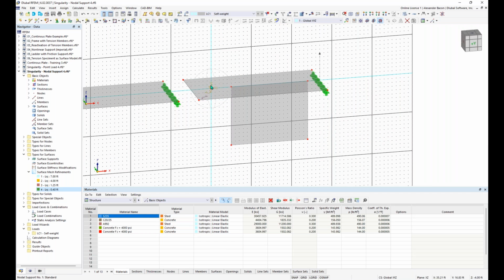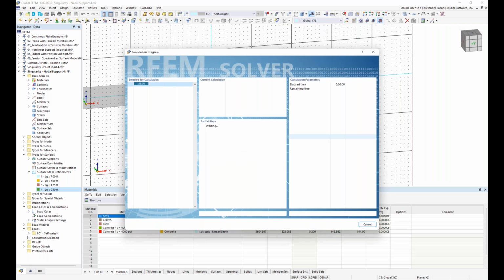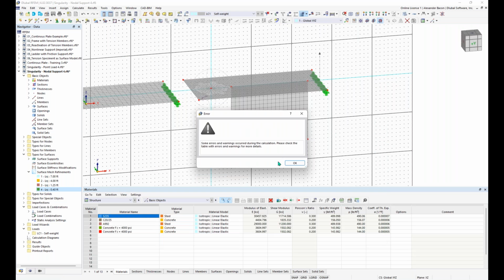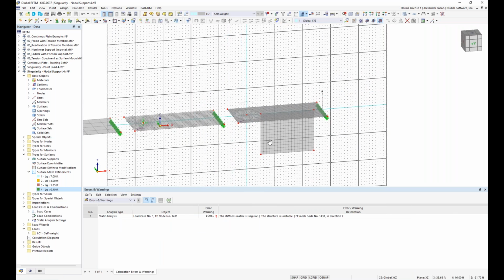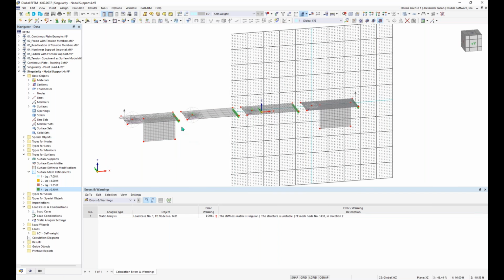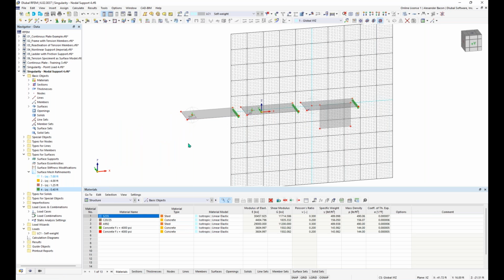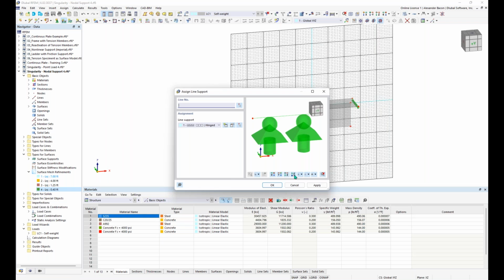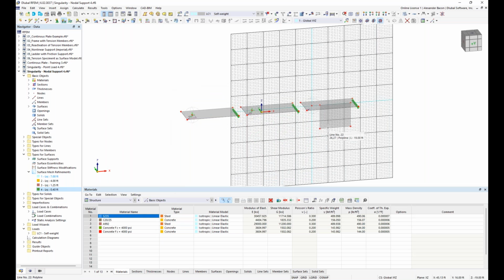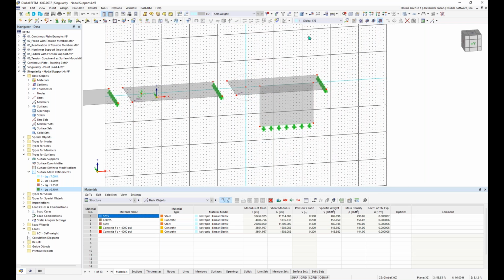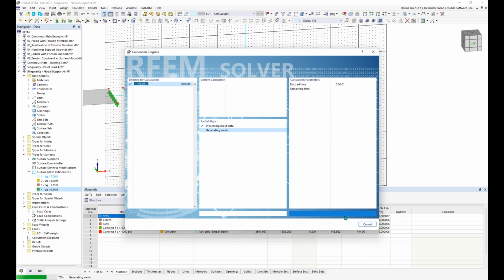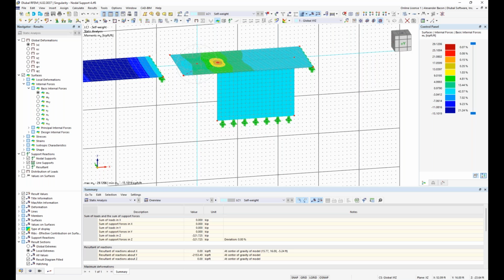Okay, so if we had a wall bearing down, or a slab bearing down on a wall like this, let's see what it looks like. So this is basically what I mean when, oh, we don't have it supported. I delete this. We need to add in a line support like that to this wall. Let's try that again. There we go.